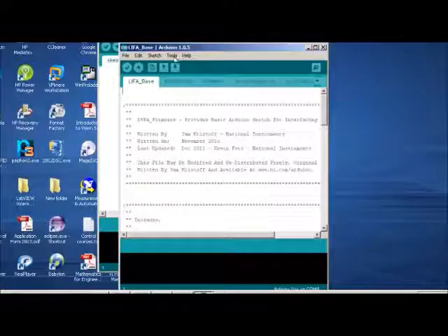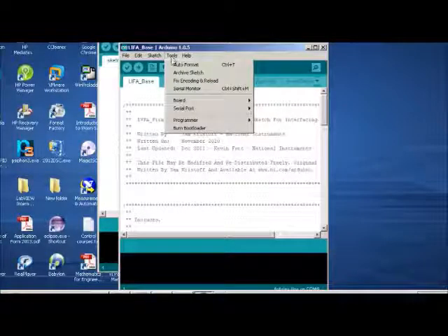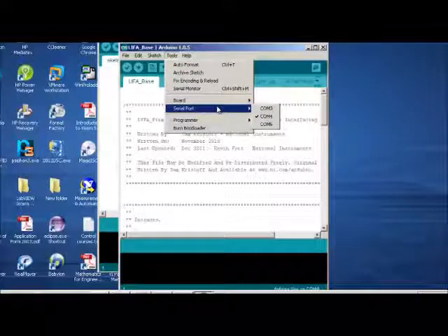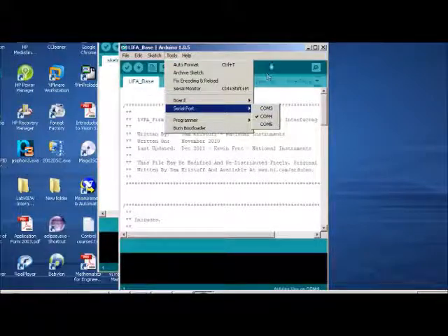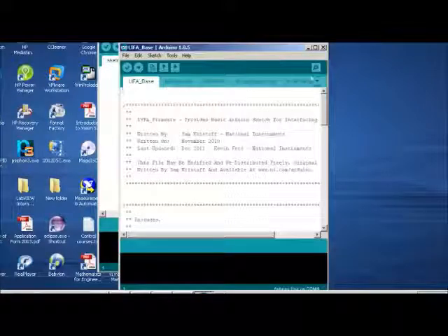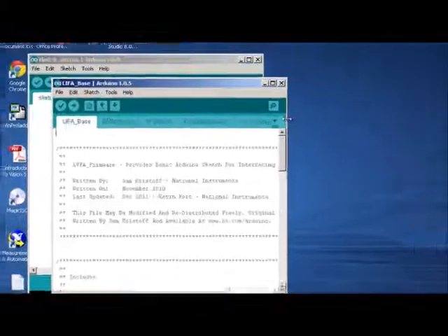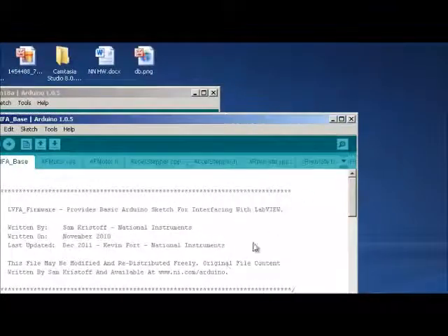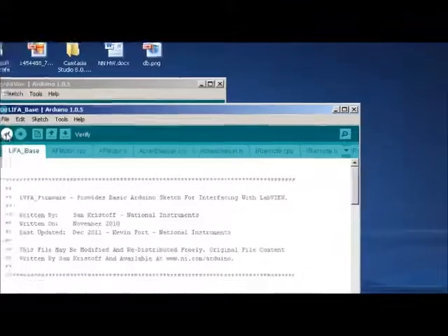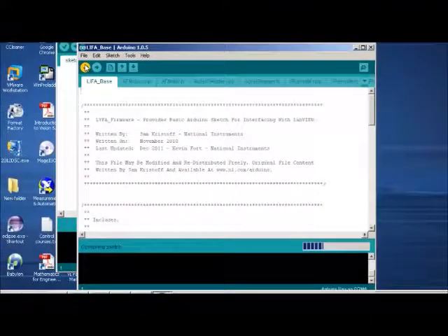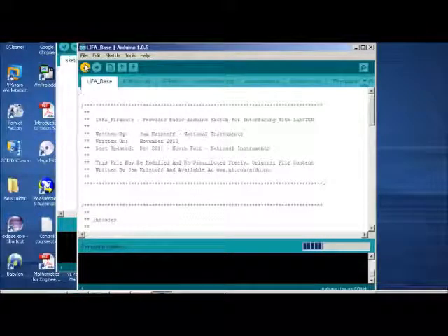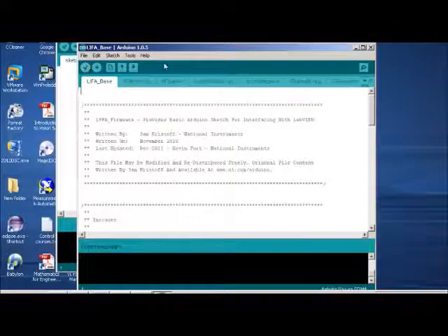So now we need to select the COM port to upload the file, and ours is COM4, and here COM4 is correct. As you can see, there are several files open in here. So we'll start by going to the verification stage to verify the code and the connection. Actually, you can skip this stage and just go to the upload stage directly.